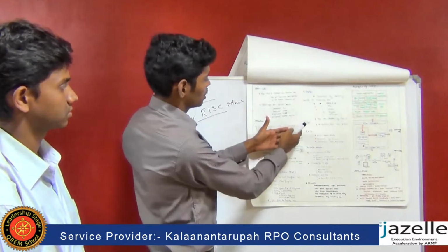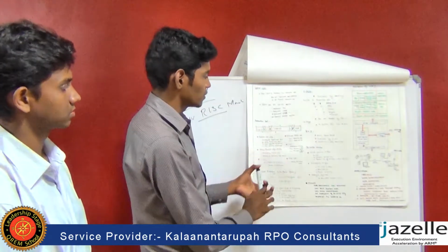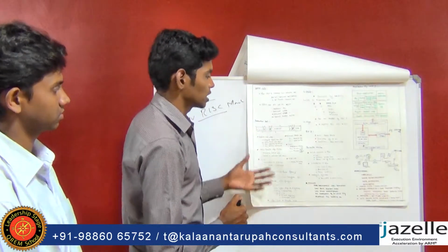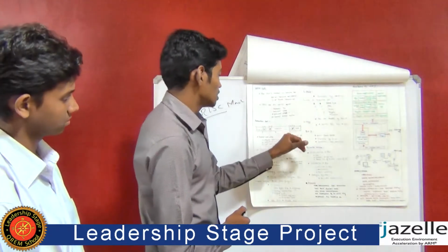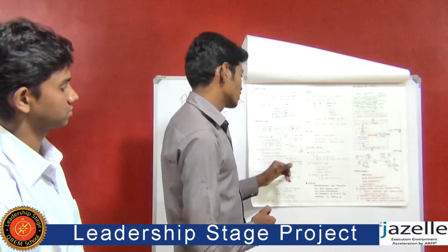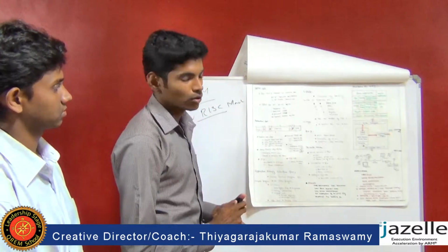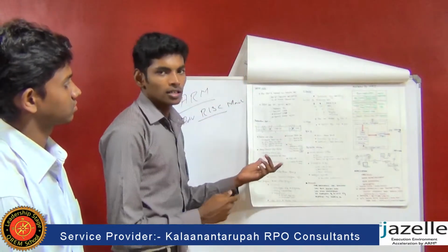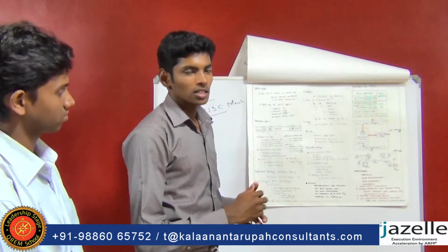The first 4 bits, as already said, specify the processor mode, whether the processor is in the ARM state, Thumb state, or Jazelle state. These are the modes specified by the mode bits. Then the T bit, the 5th bit, is present only in architecture V5. If the T bit is set to 0, the processor is in ARM state, and if the T bit is set to 1, the processor is in Thumb state.